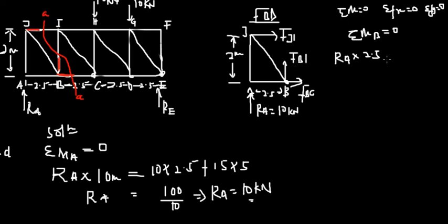Right. So we have plus FJI. So for FJI, from the point of FJI, okay, to where we are taking the moment, perpendicular to the moment is this point, okay? So from here to this point is 2 meters, okay? So we have FJI, okay, multiplying 2 meters, okay?